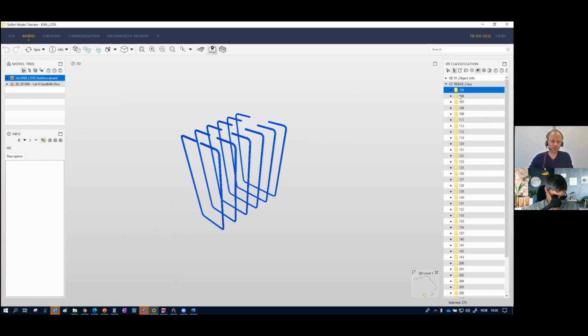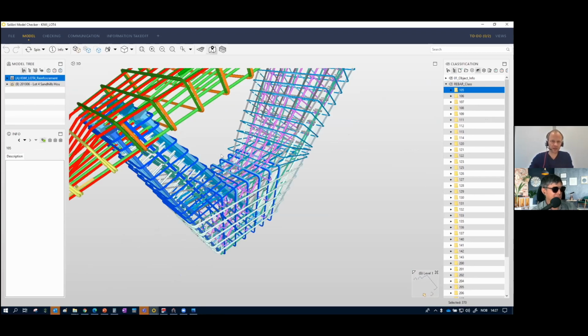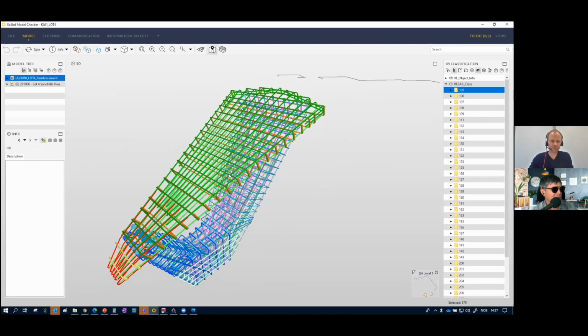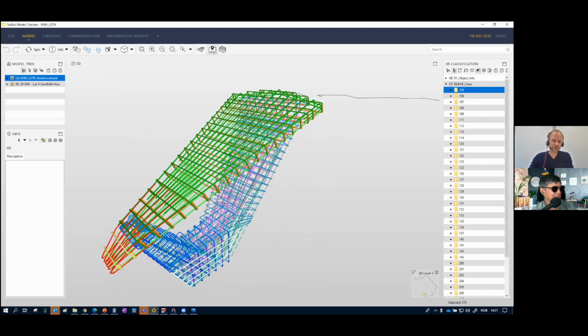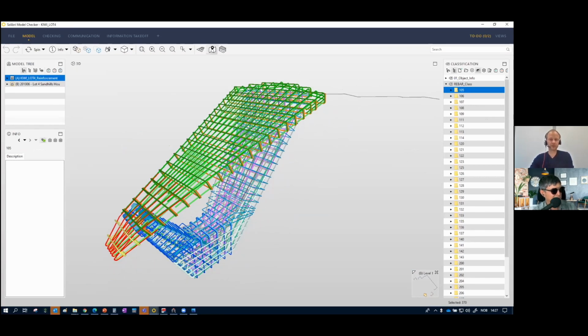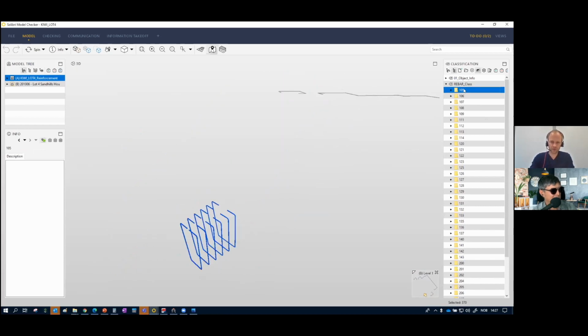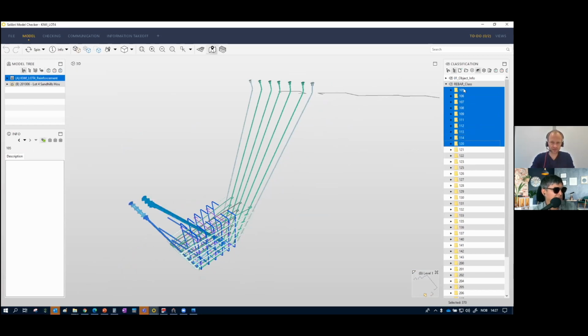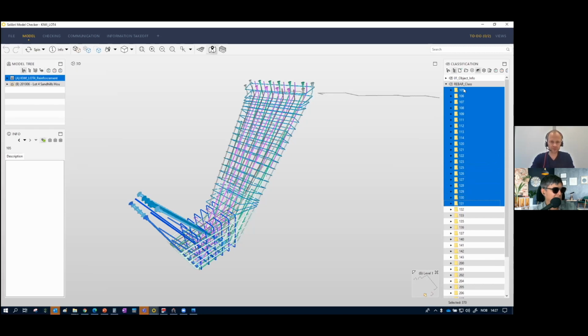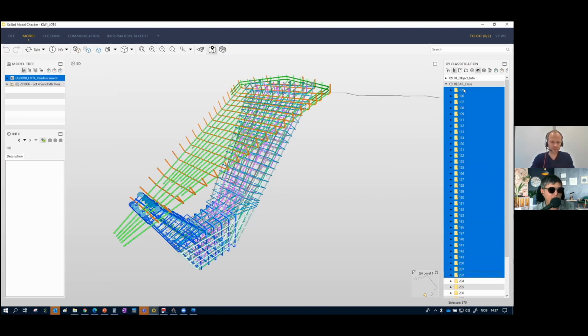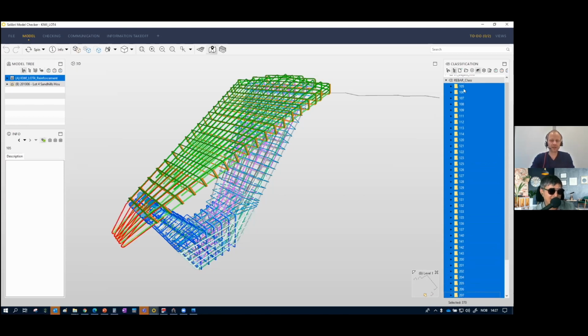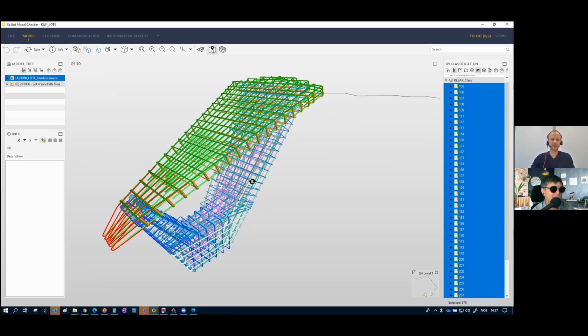because what we're able to do now is automatic rebar takeoff with bar bending schedules, so that a machine can bend all these rebars automatically. And then we do a sequence like this, so that people at site know which of the bars goes first. Oh, okay. So from up to down, you have it in the order they should place them. Yeah, at least our suggestion on how they should place them. Yeah, sure, I understand. But nice, very nice.